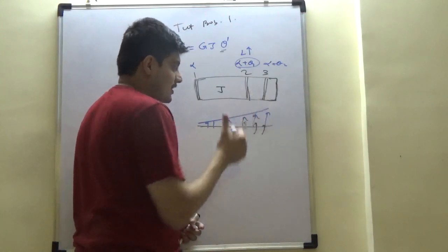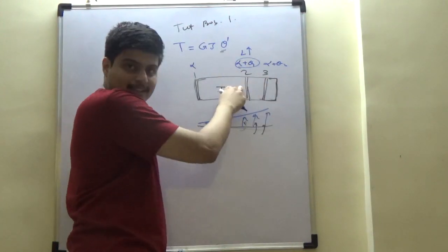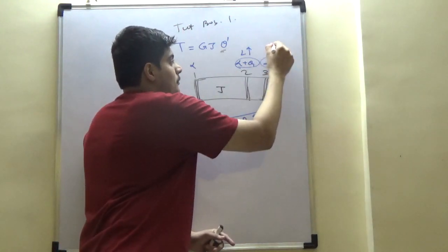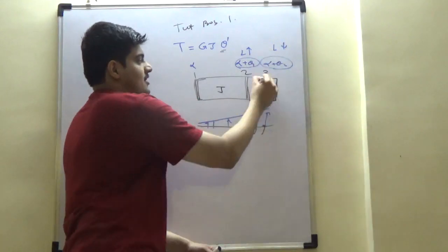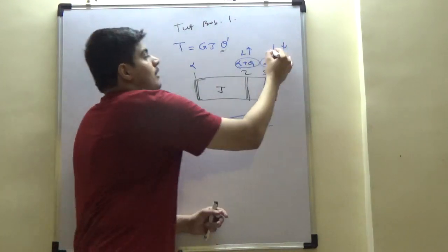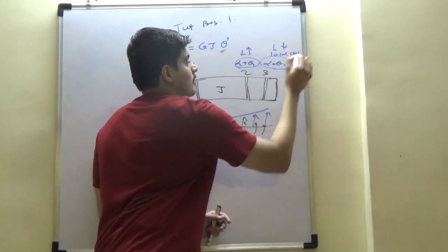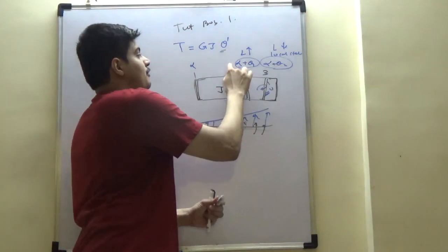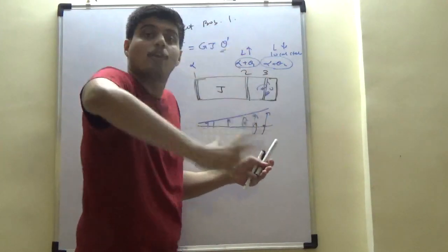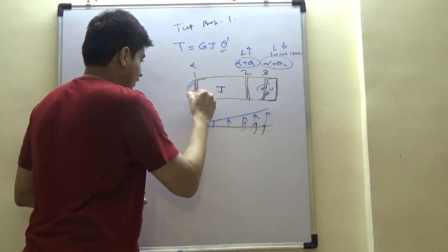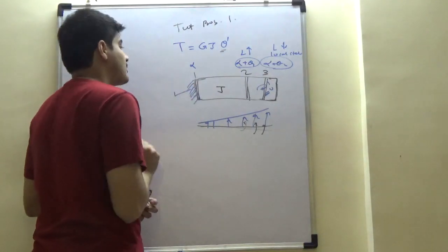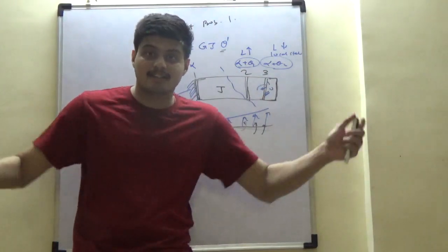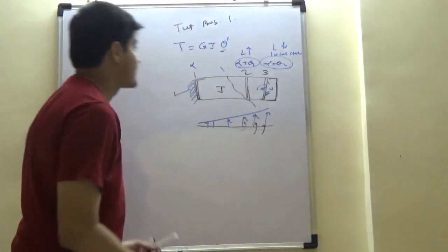It increases towards the edges slightly, further enhancing this tendency to twist further, and at some point when theta becomes large, lift drops drastically over those sections because of local stall, and then these vortices, eddies, get formed. If sufficient energy is built, this may cause resonance, increased tension here, and this energy dissipation is going to cause the wing to get fractured. That's the outcome of aeroelasticity.